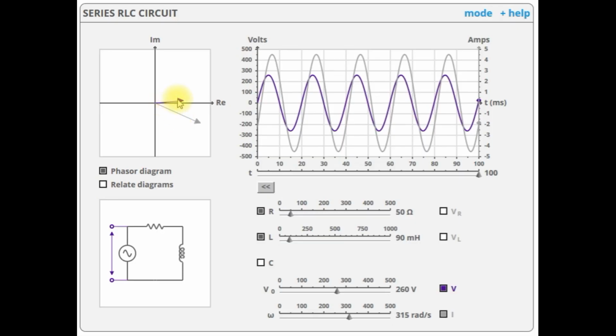This vector corresponds to the voltage waveform, and this vector corresponds to the current waveform, and you can see that this current phasor is lagging by an angle equal to say 5 degrees. So always this phase difference will be maintained because the angular velocity of both the sinusoidal waveforms is the same, and both the vectors are rotating in the anti-clockwise direction with the same speed.